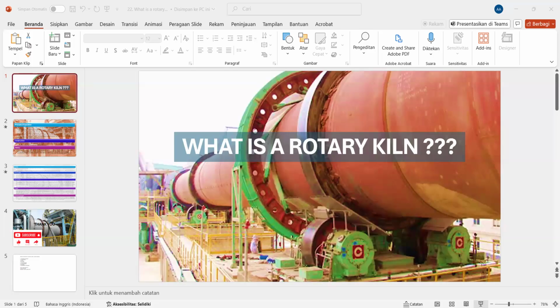The upper limit on diameter is set by the tendency of the shell to deform under its own weight into an oval cross section, with sequential flexure during rotation. The length is not necessarily limited, but it becomes difficult to cope with the changes in length on heating and cooling, typically around 0.1 to 0.5% of the length. The kiln slope is very low.